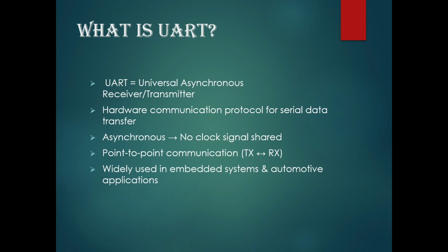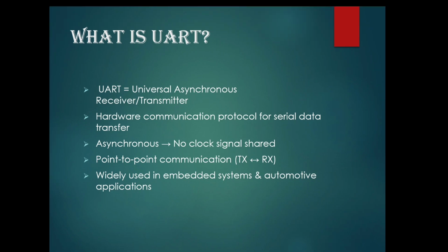It means there are only two pins, TX and RX. The TX pin is used for transmitting the data, and the RX pin for receiving. It's widely used in embedded systems and automotive applications for flashing and log related things.